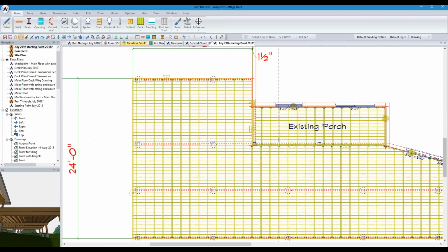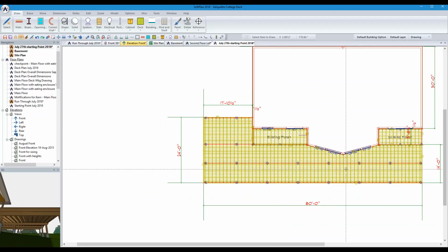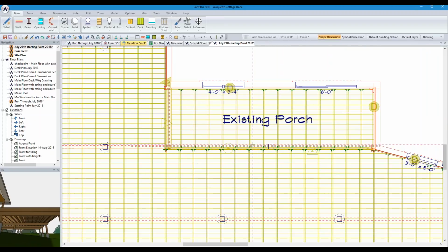We're going to go over to this one. And that just gives you an idea of how you can get your beams in place and so on. A single extension pulled off of these will also allow us to position them exactly the way we want to, no different than when you're drawing in your program. All right. Likewise, you can pull all your beam locations off. Get the object snap turned off there so it's not flashing the screen on you. And the next thing we're going to draw now is some stairs around the existing porch.